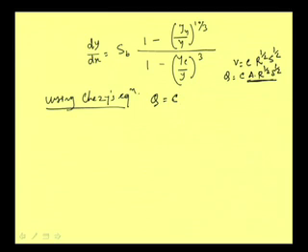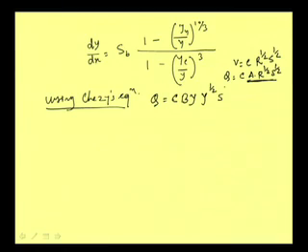So, this expression we can write with area for a wide rectangular channel, and this R, as we have already explained, can be approximated as depth in case of a wide rectangular channel. So, y to the power half and S to the power half. If we write y, that means here not uniform depth, then we can write this as SF, and of course, this is equal to C, then B, and this is becoming y, and y into y to the power half. So, it is becoming y to the power 3 by 2 and SF to the power half.